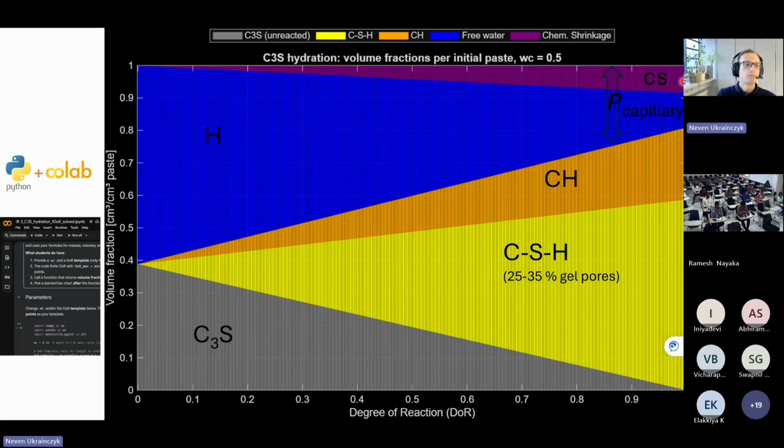So if you are not spraying concrete during the curing phase, you basically have 10% of air inside, and then also the reaction is stopped because you don't have enough water, and you have capillary forces, you have the air inside, you have chemical shrinkage, you have autogenous shrinkage, so you have initial drying shrinkage. Basically, the concrete dries from inside, and you have cracks because of the capillaries.